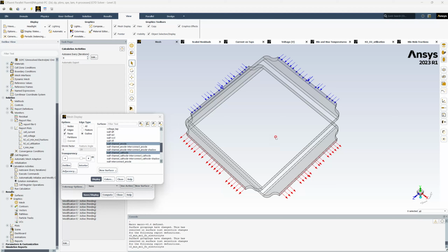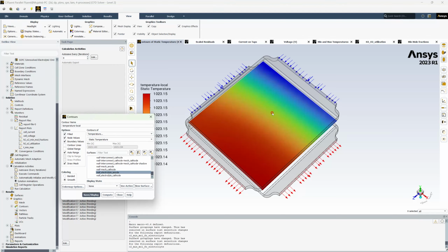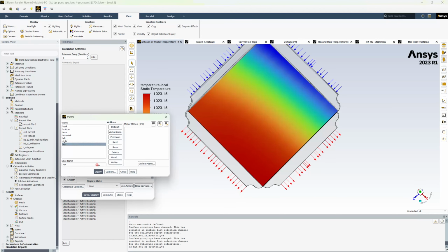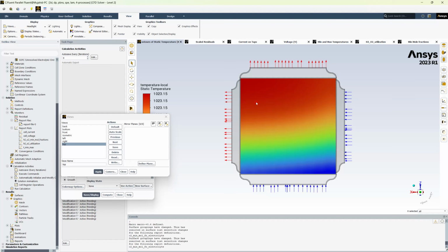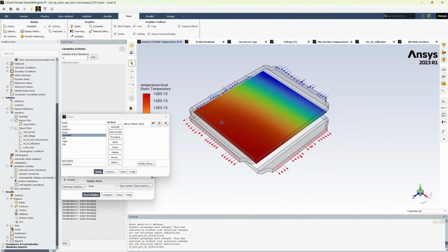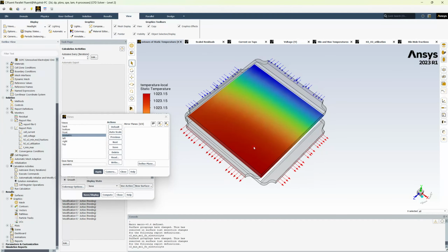But if we are looking for an isometric view, this wouldn't look good, because if we say okay and display it, now it is a little bit overlapping on the edges and it makes a confused image. But if we were looking at the top surface, now it was really good, it defines properly. So if you go to the views and select the top, apply, it looks good, but while defining all the inlet and outlet. But we are better with the isometric, apply, and we can adjust it according to ourselves for better contouring.